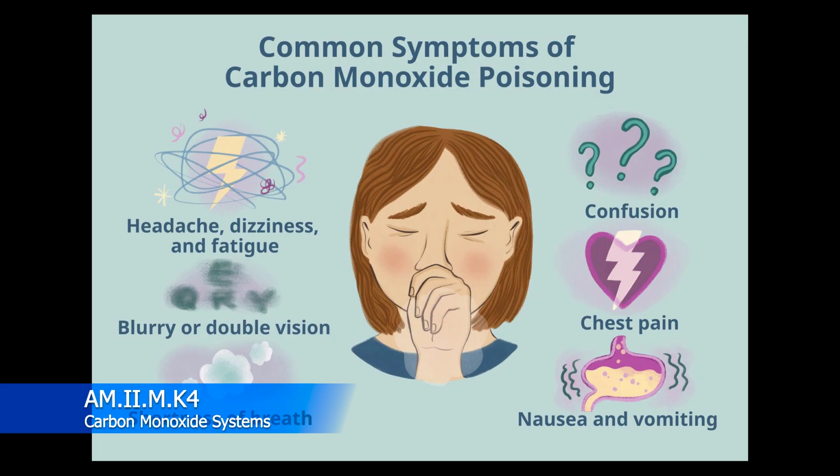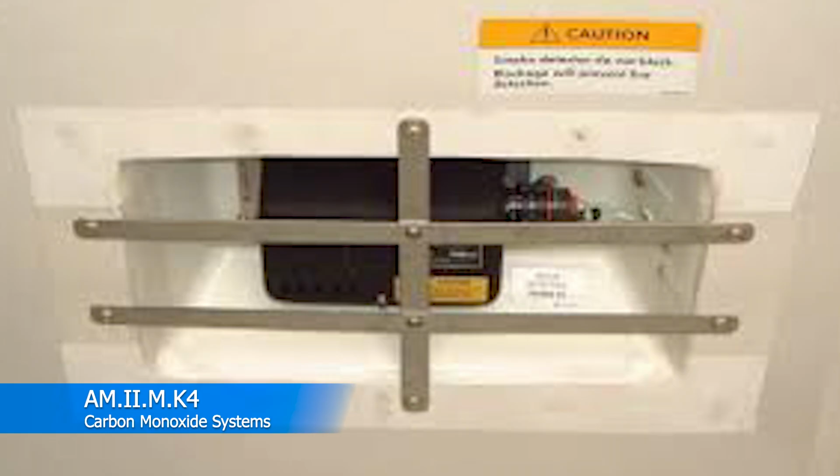Let's look at carbon monoxide detection and then smoke detection. Okay, so the first type of smoke detector is the light refraction type. The light refraction type smoke detector contains a photoelectric cell that detects light refracted by smoke particles. Once that smoke starts to refract the light into that cell, it senses enough change in the amount of light in the area it's placed that it creates an electrical current and sets off a warning light up in the cockpit. This type of smoke detector is referred to as a photoelectrical device.